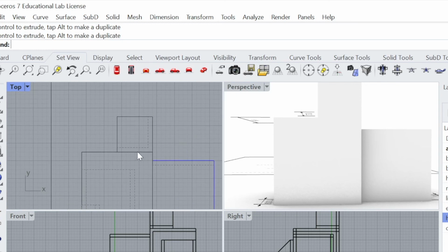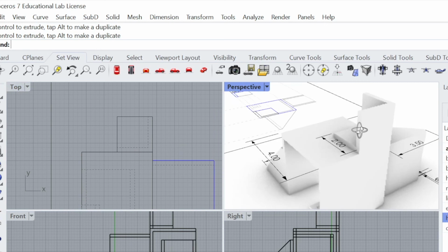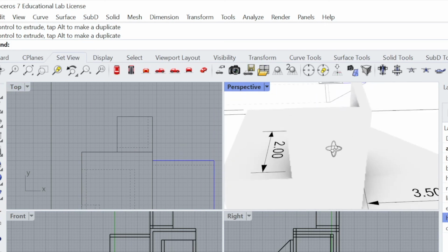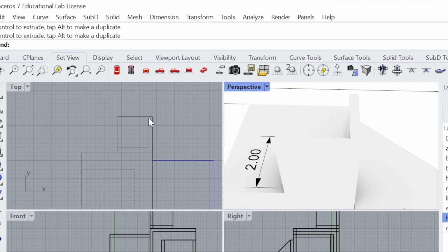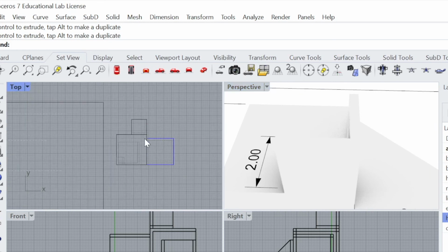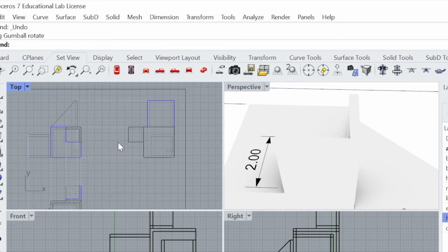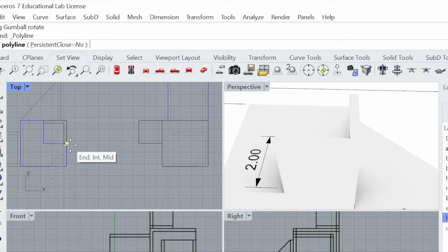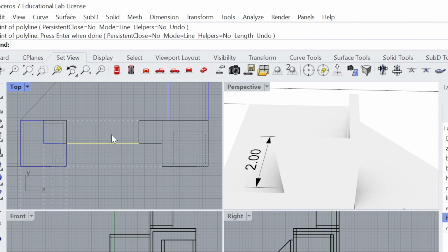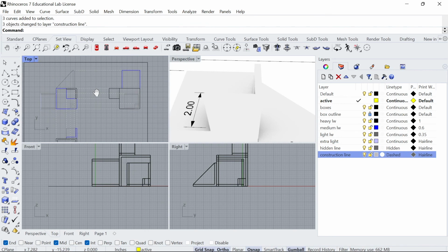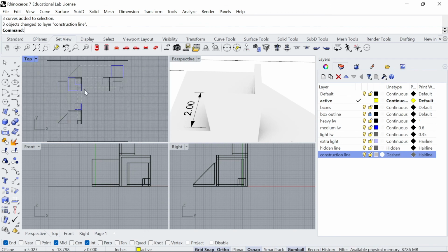And the top view has this L, which is basically the thickness of this bottom piece right here. So I dashed in the thickness of this side wall, which is this one right here, right? So I'm going to go ahead and move that back. And that's the proper way of usually drawing it. Okay, so you can add some more construction lines. Line went like that. And that pretty much covers most of that. Okay, there is an additional auxiliary view you can add to this, which I'll go over in a different part.